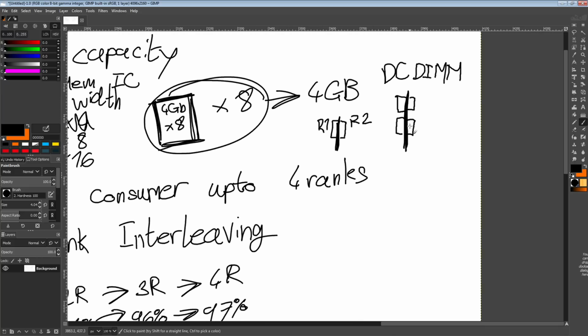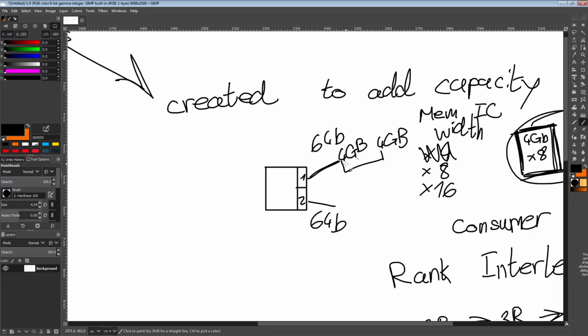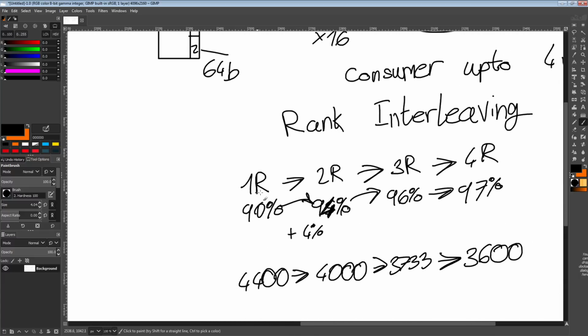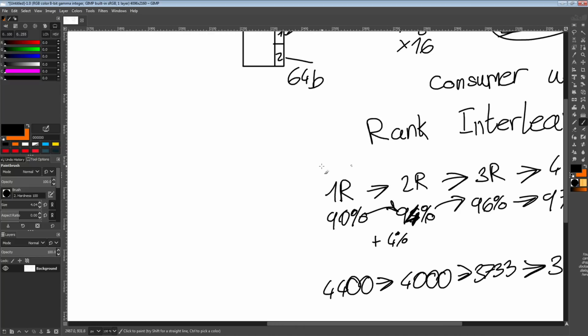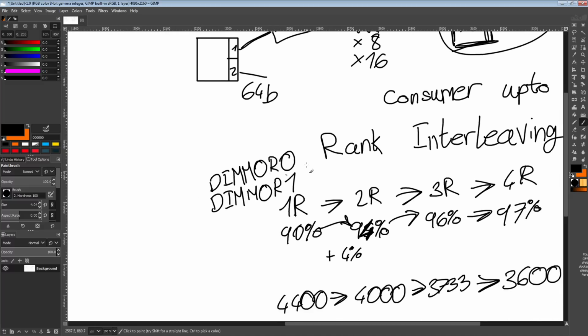And the way these work is basically they trick the... Because the funny thing is, the way the actual CPU identifies different memory ranks is it doesn't identify them as rank 1, rank 2, rank 3, rank 4. It basically identifies the groups of memory chips as DIMM first, as a memory stick, and then you have DIMM 0 rank 0, DIMM 0 rank 1. Right, so you can have DIMM 0 rank 0, DIMM 0 rank 1, and then on that same channel you would have DIMM 1 rank 0, DIMM 1 rank 1, and that's specific to that channel.